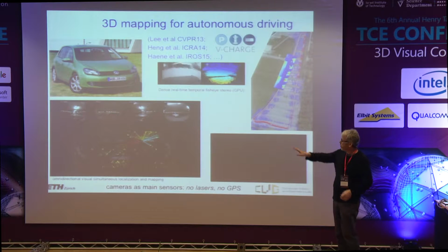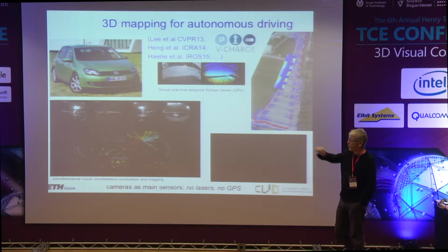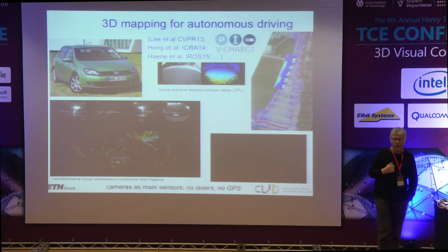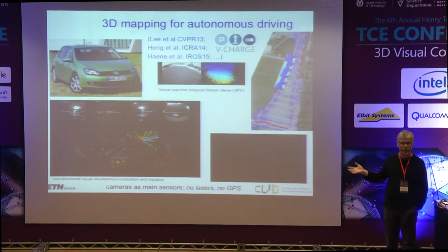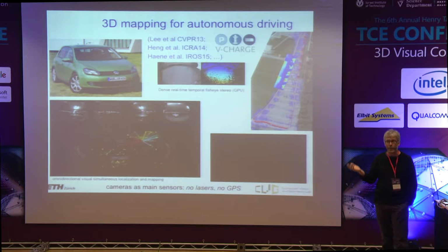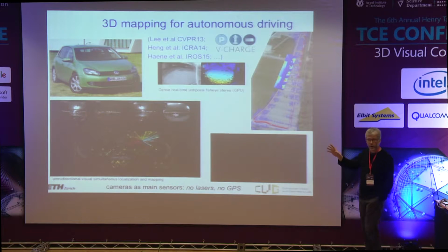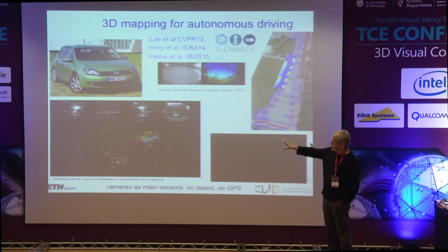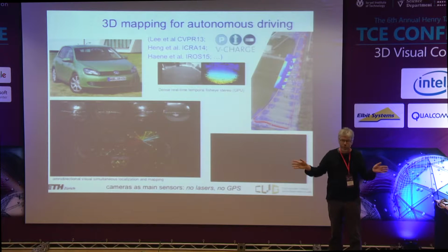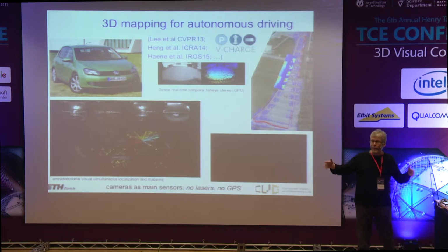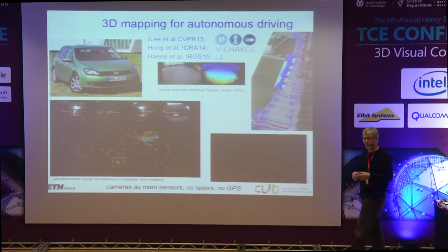Okay. So what we do on the one hand is use the omnidirectional cameras for localization. Notice we're talking about indoor parking garages, things like that, so no GPS available. So we need to localize based on pure vision. So we build maps and then we calibrate. All these things are done fully autonomously. We recalibrate as the cameras are mounted on the rear view mirrors, so you have a slightly different calibration every time you start your car.